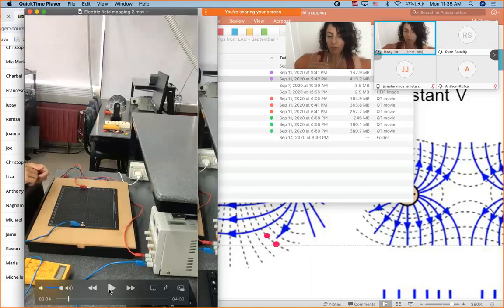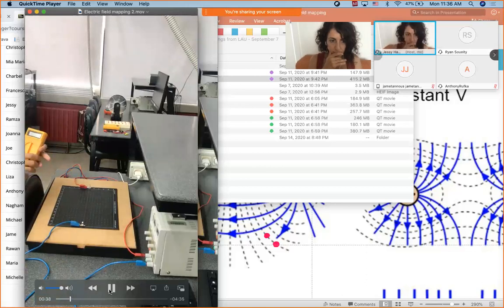So I know the difference is 20 volts, but I don't know what each represents. It could be positive 10 volts, negative 10 volts, you know? It could be, I don't know, 11 volts versus negative 9. I know the difference is 20, and this is what I care about. My job is to use the voltmeter, the multimeter on volts, to be able to try to do some measurements.